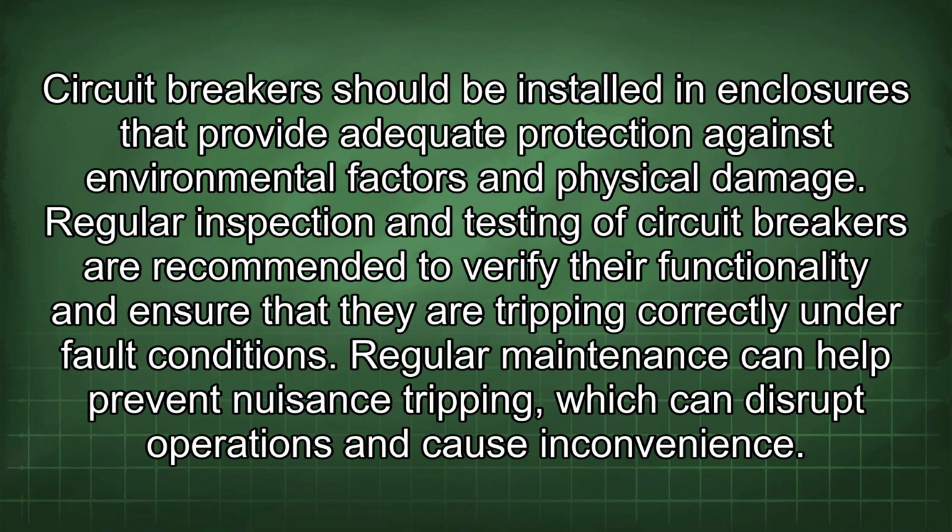Circuit breakers should be installed in enclosures that provide adequate protection against environmental factors and physical damage. Regular inspection and testing of circuit breakers are recommended to verify their functionality and ensure that they are tripping correctly under fault conditions. Regular maintenance can help prevent nuisance tripping, which can disrupt operations and cause inconvenience.